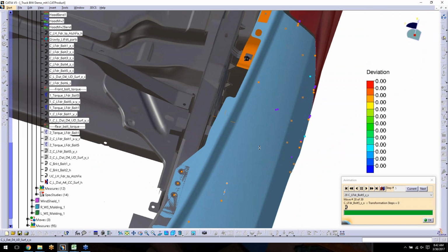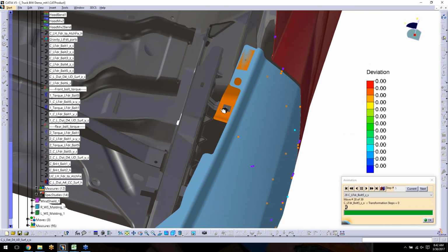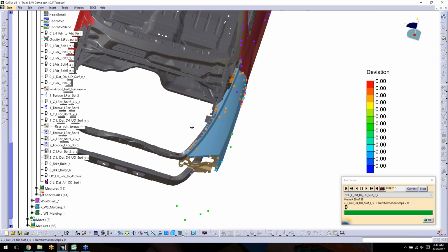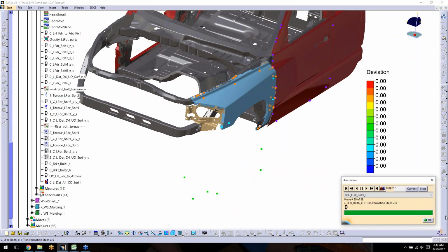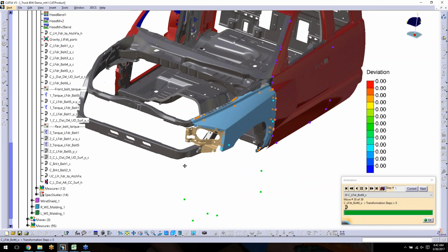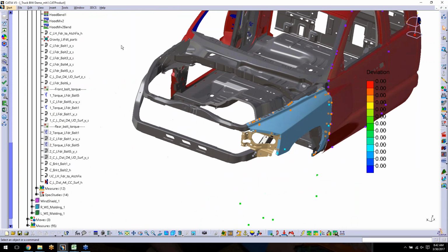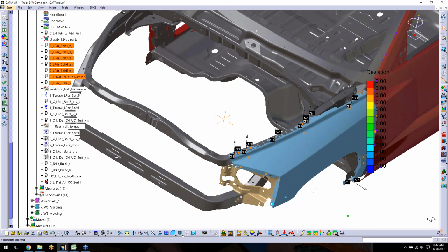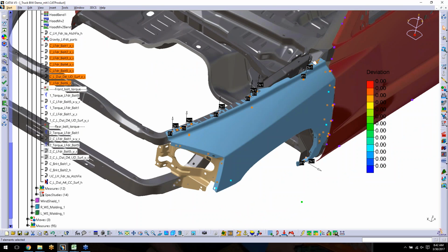This is the one that contributes to the flush measurement. This is the one that actually sets the flush. So this is attached also in Z direction. Everything is in Z direction for now. Up to this point, we have the clamp, the hard clamp, and basically setting the fender onto its locators. So touch condition here, and all of these other areas.